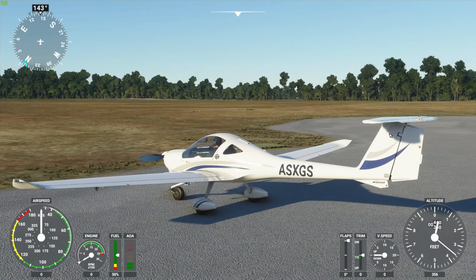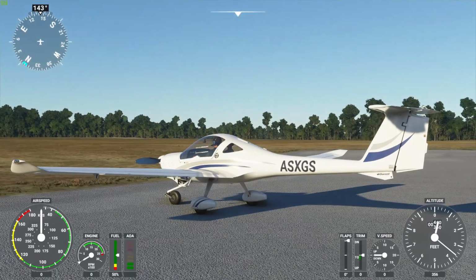I think that's going to be well above the dirty air. So when the wing stalls, you get dirty air rolling off the wings, and if the elevator's here, then that will get hit by that dirty air and lose its effectiveness. So by mounting it up high like that, then the elevator is going to be well clear of the dirty air coming off a stalled wing, and therefore give us elevator authority even as the aircraft stalls aerodynamically. So that's probably why it's mounted up the top.